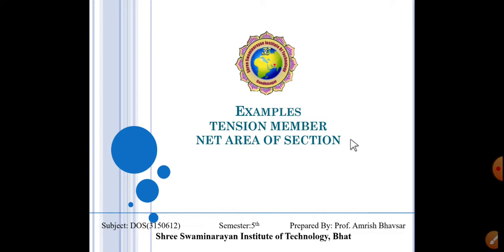In IS 800 2007, they have told us that whenever this kind of rupture occurs in our joint or in our member, we must calculate that net area in different ways, which is given on page number 33 in IS 800 2007.